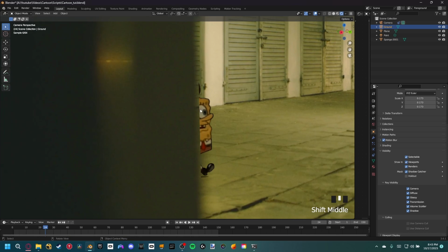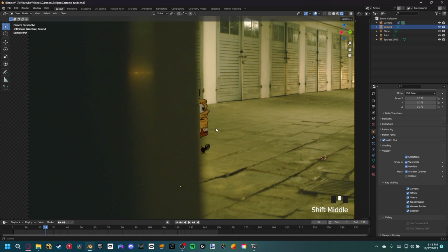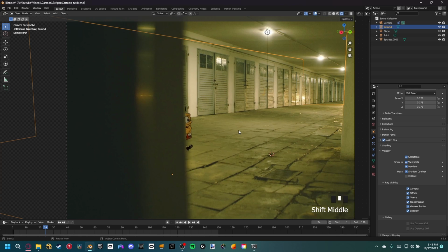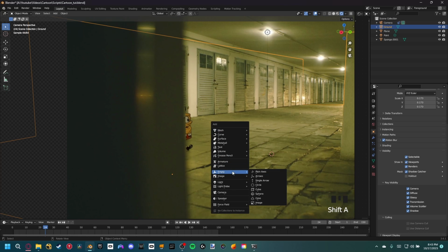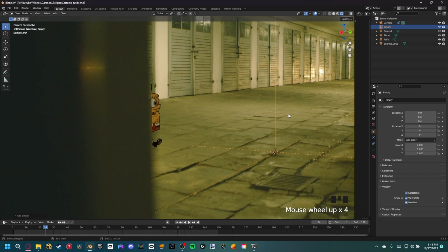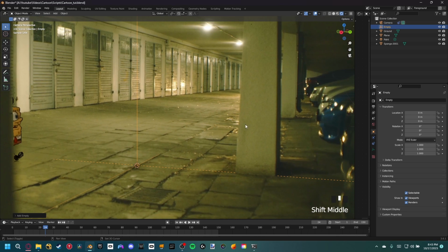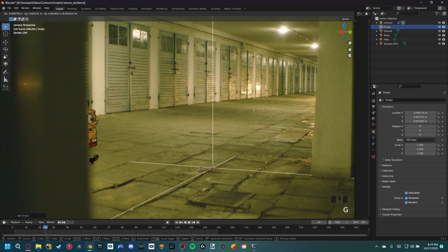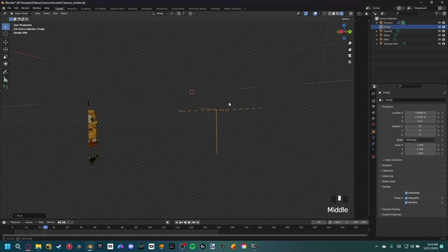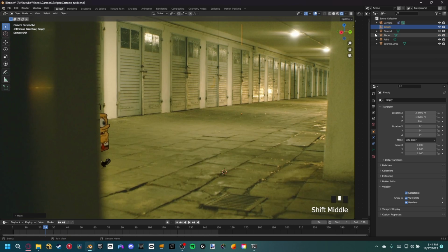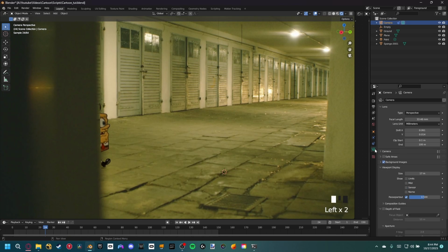It's a very solid line right there, and so let's actually go ahead and match the depth of field of our camera. So to do that, I'm going to go ahead and add an empty plane axis, and we can tell that the focus is roughly around this area back there. There's not really an in focus part of this image. It's all kind of blurry, so I'm just going to G Shift Z and then position it somewhere back there.